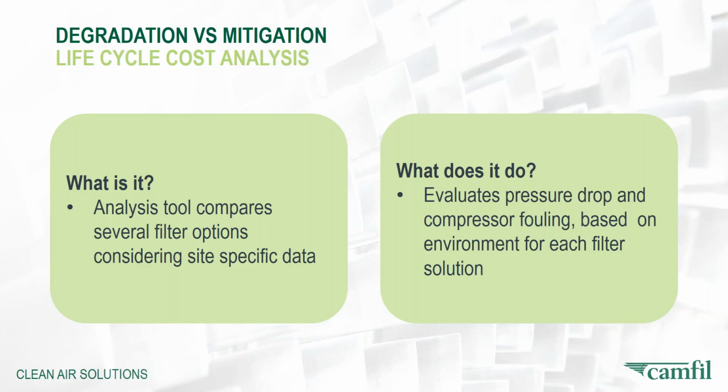This is a tool that Camfield developed a number of years ago and has refined continuously. It allows us to compare several different filter options under site-specific conditions. We do it by evaluating the effects of pressure drop and compressor fouling for that particular environment. And it allows us to show you, from a dollar value or monetary value standpoint, what the cost effects can be of specific choices you make for filters.